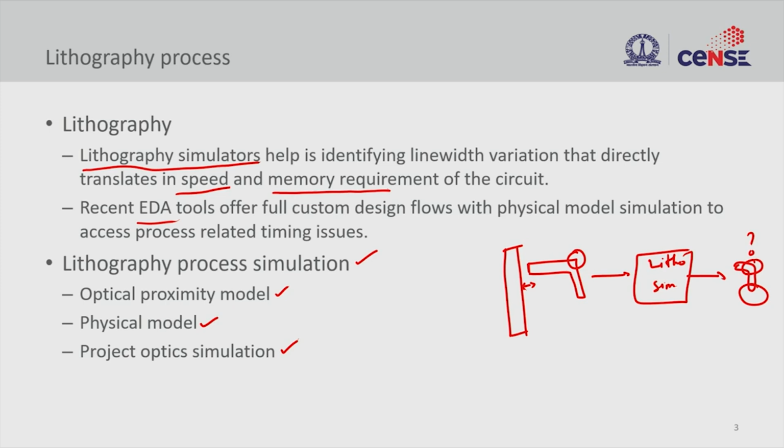In advanced tools, you can actually extract all these defect points, or locations that you need to attend to, right. For instance, if there is a very narrow gap, and post simulation you find out that this gap would merge, creating a short circuit, you will go back to your design.